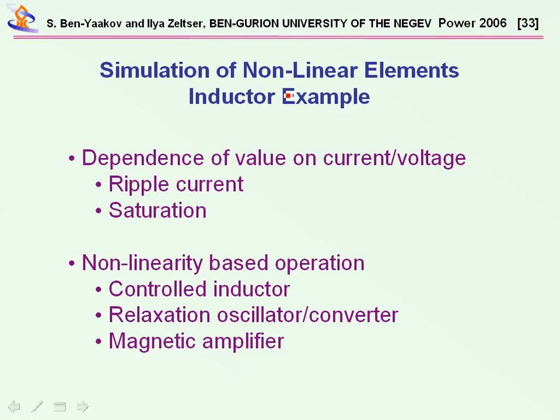Now, I'm talking here as an example about an inductor. Why would you like to simulate a nonlinear inductor? Well, there are many reasons for that. For one thing, real, physical inductors are nonlinear, and they depend on the current, and consequently, things like the ripple will change as a function of the current flowing through the inductor. It might go into saturation, and this phenomenon you would like to see by simulation.